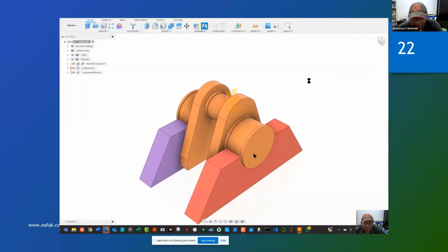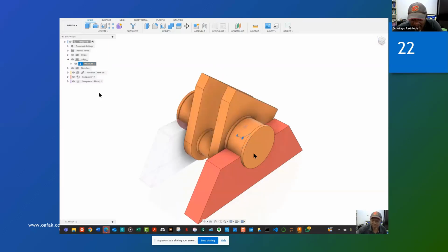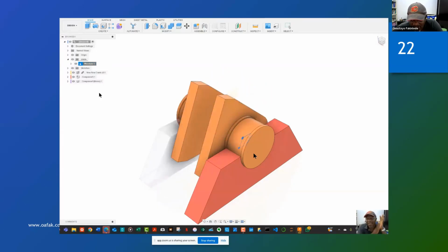You say okay, you've turned this thing on again, and then you can now go and test the joint. Right click on the joint, revolute, right click on it, and go and animate the joint. So you see, that's an animation of the joint now. It's showing the two of them, and it's showing that the rotor will move on the stator there.